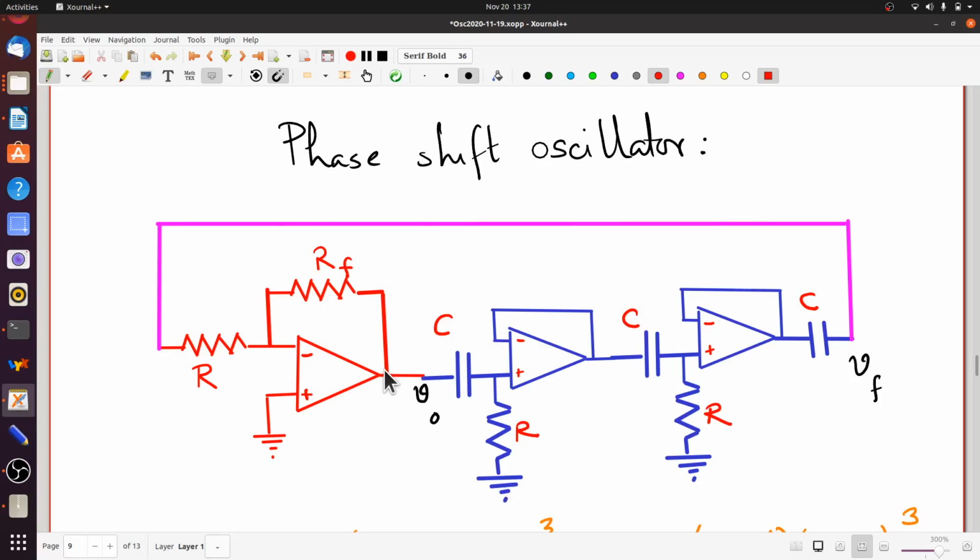So there's a 180 degree phase shift, but the CR will try to move the phase back forward again, right? Because R leads, the output of the CR leads whatever is being an input to it.